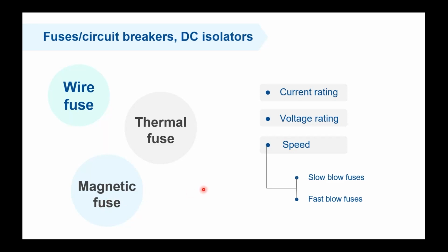So traditionally, a fuse contains a wire or a strip of metal that melts as soon as unacceptable current passes through the fuse. And when the wire in the fuse has melted, the electrical circuit has been broken and no more current will flow in the circuit.